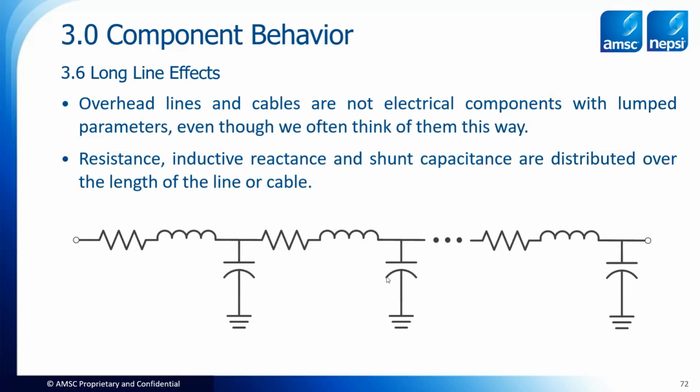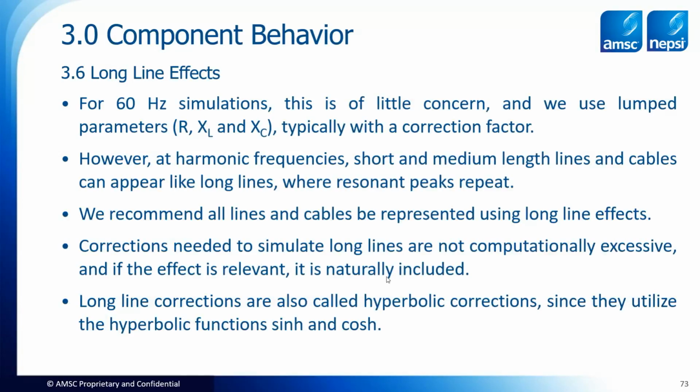You could do a short line model versus a long line model. In this case, my recommendation is for every simulation you ever perform, you use long line methods, okay? So for 60 hertz simulations, this is very little concern, but not for harmonics.